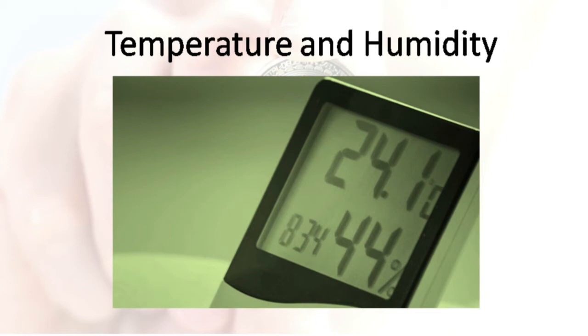I would recommend that at the intake vents of your rigs, you should install sensors measuring the supply air temperature. You should also set up multiple alerts that will notify you on your mobile device or similar as to whether the temperature or humidity rises or decreases to a point where the activity of the mining rigs is at risk.